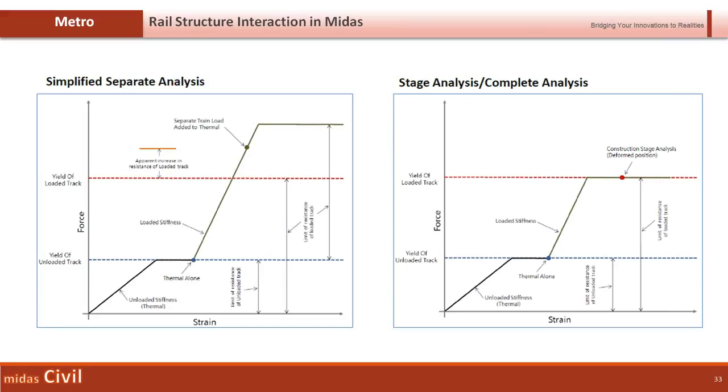It will vary depending upon the track structure, the loading or unloading, the degree of maintenance of ballast, ballast-less track or track installation method, and the loading frequency. So to account for all those non-linear behaviors of interaction, we give multilinear elastic links.